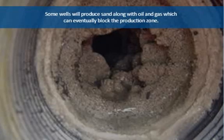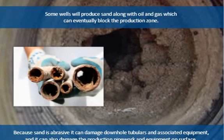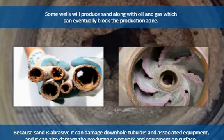Some wells will produce sand along with oil and gas, which can eventually block the production zone. Because sand is abrasive, it can damage downhole tubulars and associated equipment, and it can also damage the production pipework and equipment on surface. The sand can either be removed mechanically using wireline or circulated out of the well using coiled tubing.